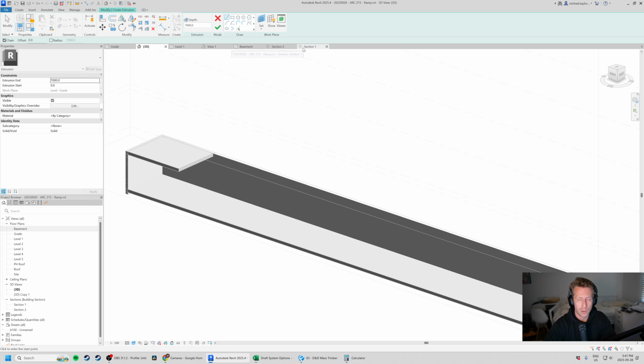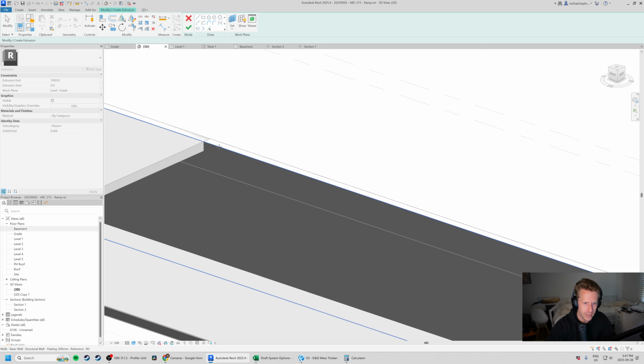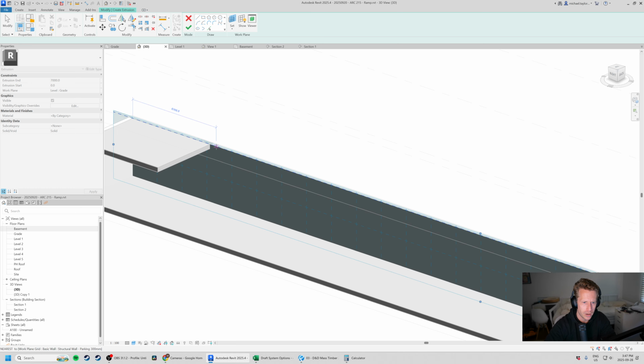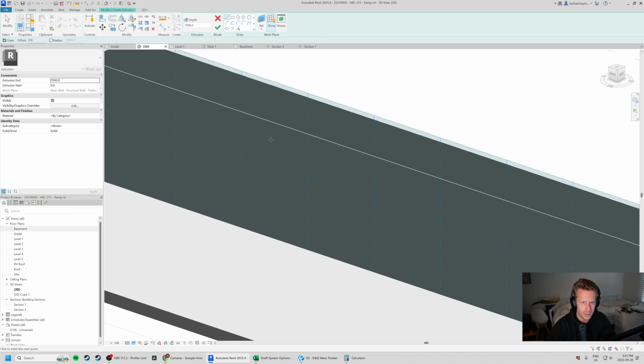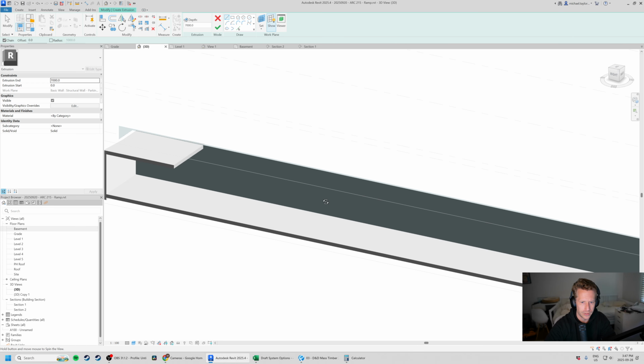Now, if you remember from the family of columns that we made, we had to set a work plane. Here we don't really have a work plane we can use for this task because I haven't created one. So I'm just going to keep this loose and drop down from set here, hit pick a plane, and you can model on a surface. So imagine that unlike our reference plane, we're now choosing the inside face of our parking lot shear wall here. I click this, and now you can see, if I turn it on, it's allowing me to draw on the face of this inside wall.